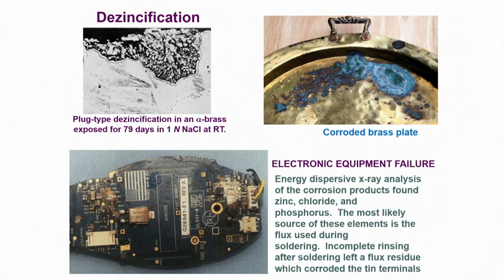Materials can degrade over a period of time because of various other possibilities. So even before corrosion starts, because of interaction with the environment, there could be gradual loss of alloying elements. For example, when we talk of brass, we know that brass is copper alloyed with zinc, and this zinc is the element which actually provides the strength and various other important properties.